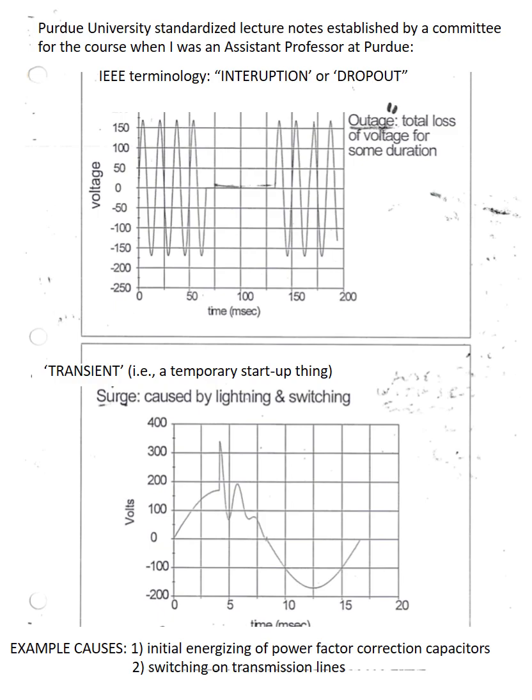But what you have is real and reactive loads, reactive loads of inductance and capacitance in it. The real is pure resistance. It doesn't cause problems. But when you have inductance or capacitance, like motors in a factory, you have inductance, and then you want to cancel out the negative effect with capacitance if you have too many inductors, motors.